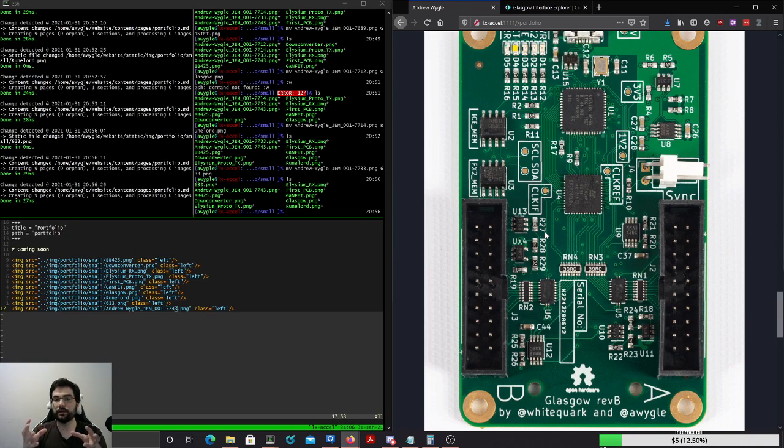Yeah, so the vapor comes up, it hits the board, which is cold, and then it condenses on the board, and just because of the physics of it, that brings the board up to temperature. It does it in a really all-inclusive way. It transfers a lot of heat very quickly, but also in a very controlled way, because purely by the physics of it, you cannot overcook the board. It's extremely safe, extremely effective, and it gets really even heat distribution.